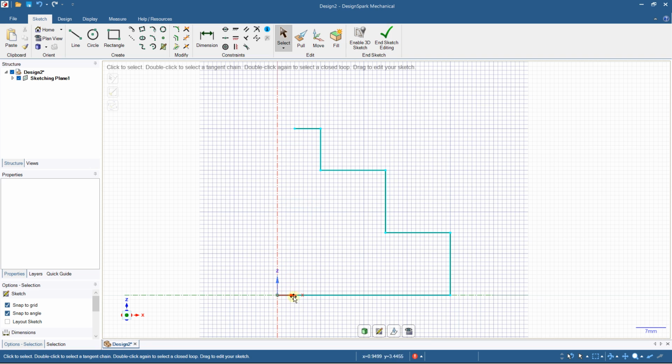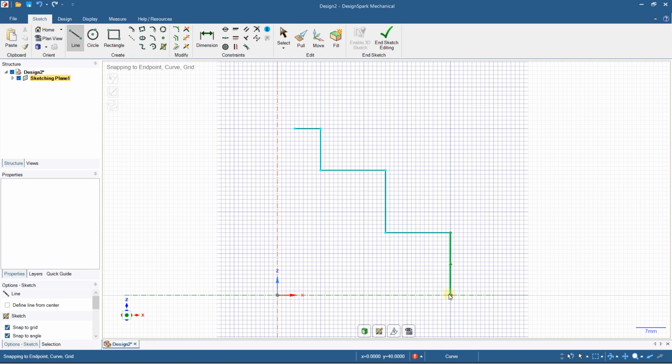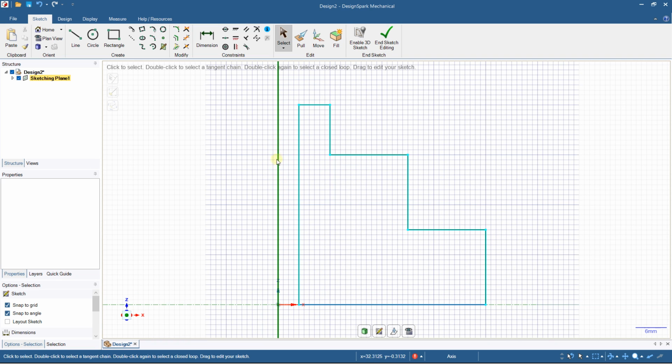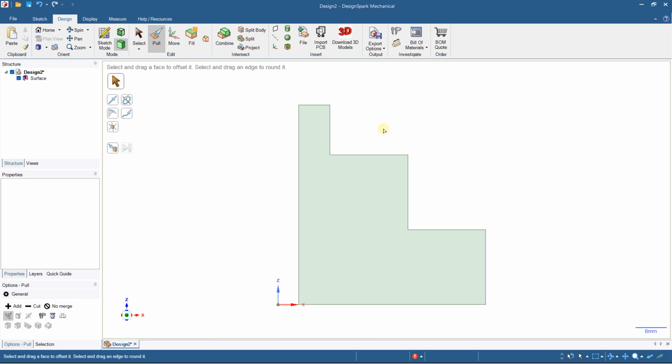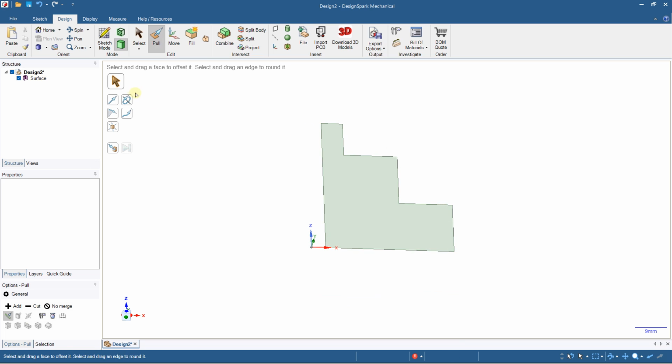One of the best things to do is to delete this one, and just create another circle from this to, for example, here, and here. So now, as you can see, I have a little space between this line and the Z-axis. And if I use my revolution, I can create a hole in the middle. Select the pull tool, revolve again, and activate the axis to rotate about. And this time you don't apply this one, but you click on the Z-axis.